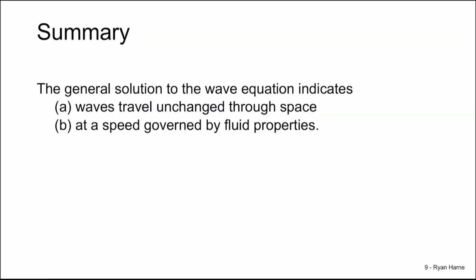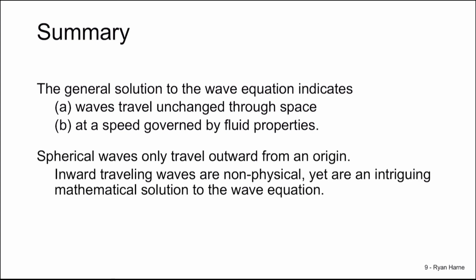So let's summarize what we've learned in this video. We've learned that the general solution to the wave equation indicates that waves travel unchanged through space, and they travel at a speed, the phase speed or sound speed, governed by the fluid properties. Spherical waves only travel outward from an origin. Inward traveling waves are non-physical, although they are, of course, an intriguing mathematical solution to the wave equation, and in some cases are an interesting point of research pursuits.